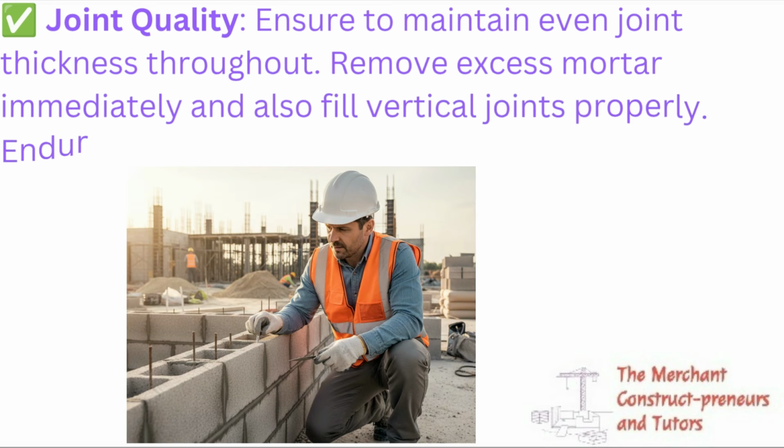This is to ensure that the blocks are properly bonded using the mortar, because as you are laying the blocks, you have space to include mortar. That mortar joins the blocks together. Ensure that it is neat. You remove excess mortar immediately, and also fill those joints, especially the parts where you don't have enough mortar. You ensure that the mortar enters into it, because if the joint